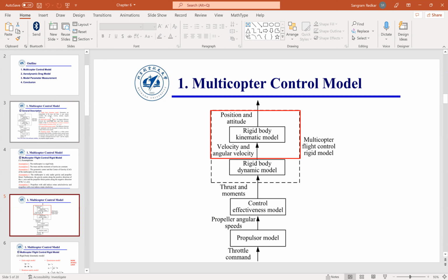So ignoring mass and moment of inertia, we just focus on the kinematic model. Kinematics is motion. So you have a linear motion and you have angular motion. So those are the kinematics parameters. Second part is first you have to resolve the kinematics. Once you know the kinematics, you use that information to solve for the dynamic equations. There are two dynamic equations. One is the dynamic equation for translational dynamics.